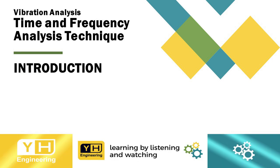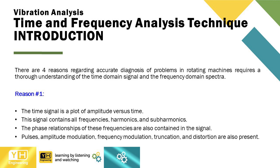Vibration analysis. Time and frequency analysis technique. Introduction. There are 4 reasons why accurate diagnosis of problems in rotating machines requires a thorough understanding of the time domain signal and the frequency domain spectra. Reason number 1: the time signal is a plot of amplitude versus time. This signal contains all frequencies, harmonics, and subharmonics. The phase relationships of these frequencies are also contained in the signal. Pulses, amplitude modulation, frequency modulation, truncation, and distortion are also present.